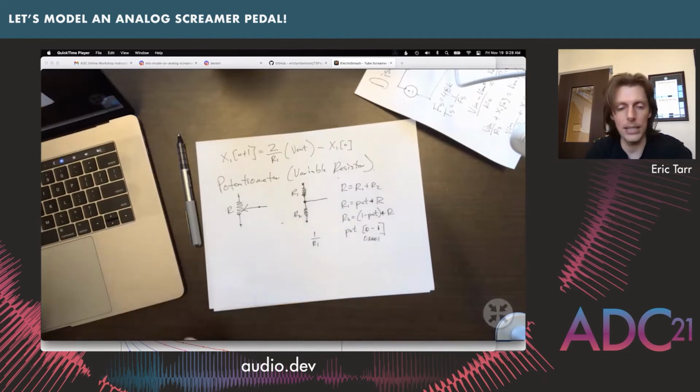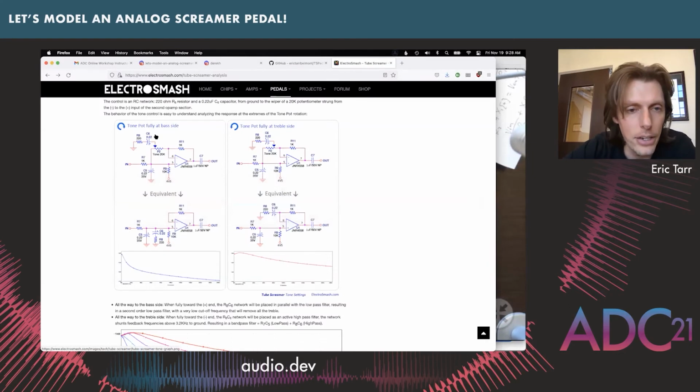So that's the extreme case when you're able to break it apart, and you have this flow of current that goes from our input through this path down this capacitor right here, C6, and then through R8 down here. But then we don't have anything going through the path on this top branch. The other case, when you turn the potentiometer the entire other direction, then we're not going to have current that is able to flow that way. And we just have the current flowing down through this path, up through this capacitor, up through this potentiometer.